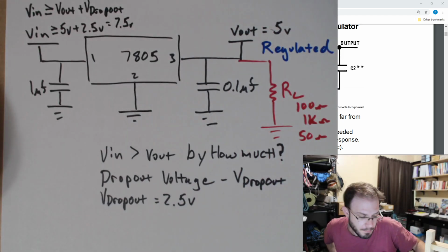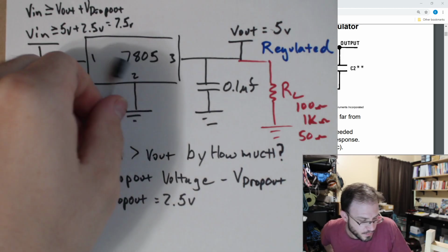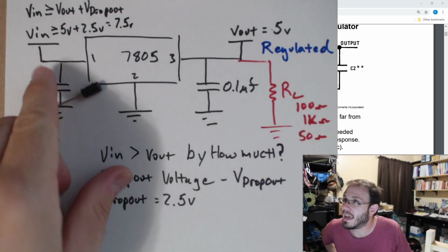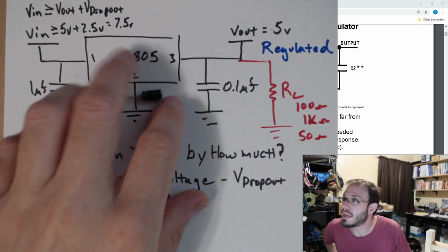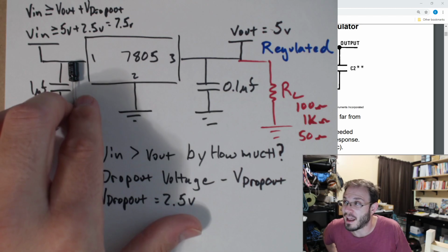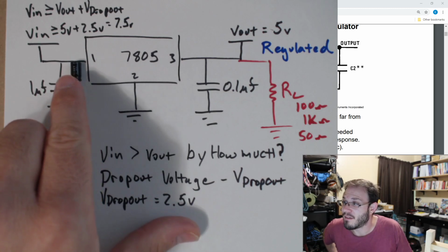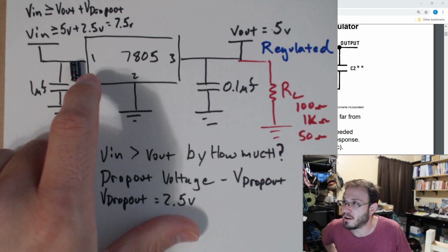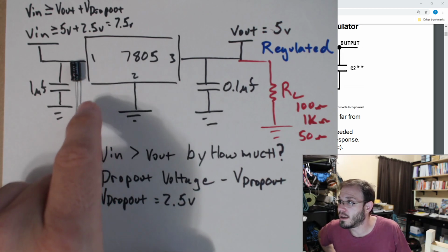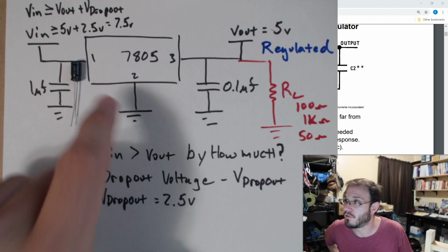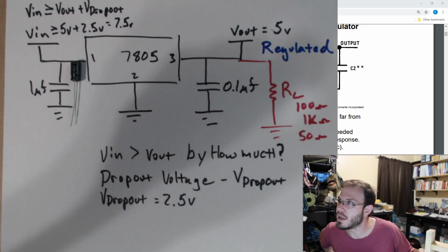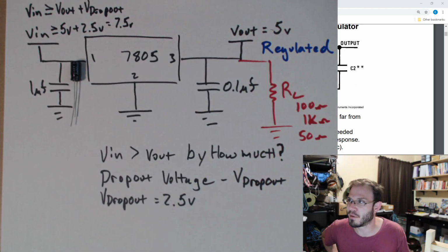for something like 1 microfarad, you might have to use something like an electrolytic cap. The tolerance on these caps is plus 40% minus 30%. Plus 40%. I'm not making this up. If I say that this is a 10 microfarad cap, it might actually be 14 microfarad, or it could be 7 microfarad.